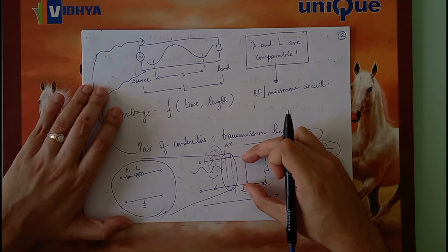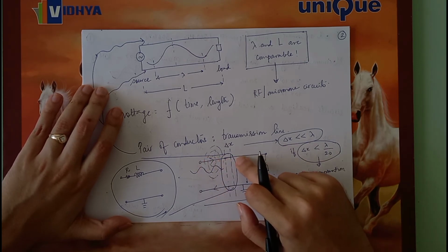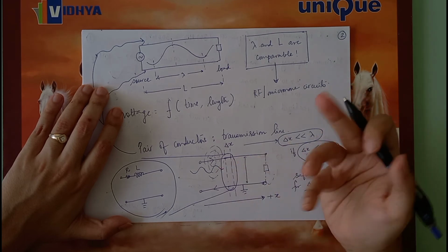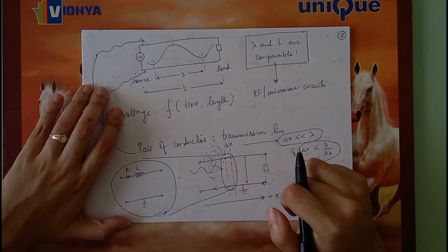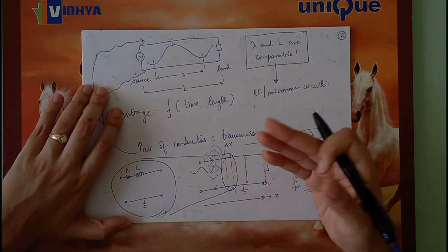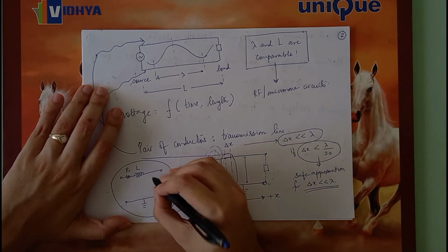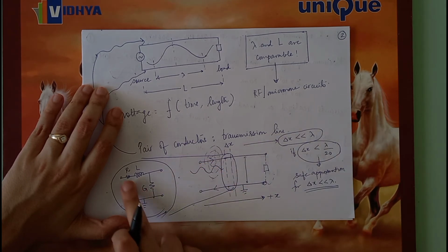Now what happens is, an insulator should have very high resistance. So just like for wires, the unwanted behavior is resistance. For an insulator, the unwanted electrical property that it should not exhibit is something called conductance. That is the reciprocal of resistance. Remember, this G is not 1 by R because this G is of the medium that is between the wires.